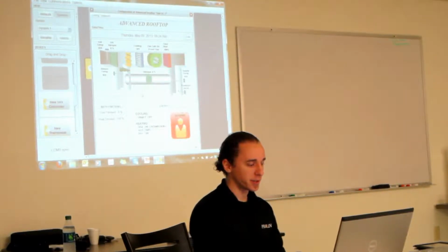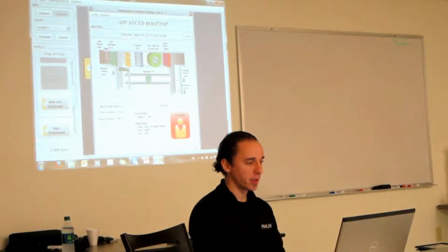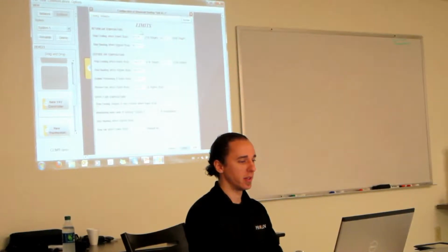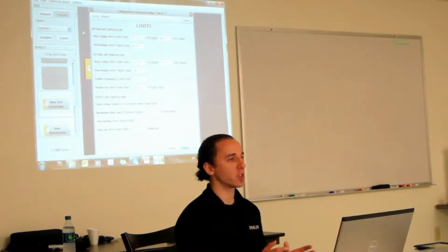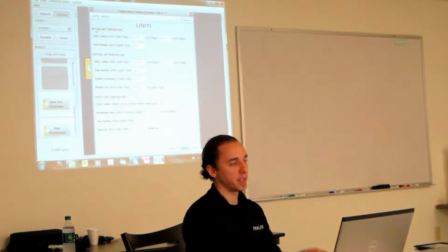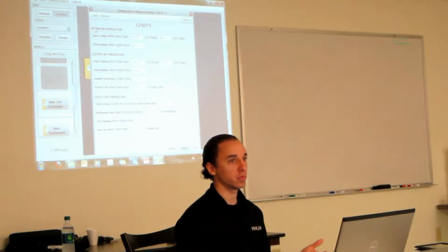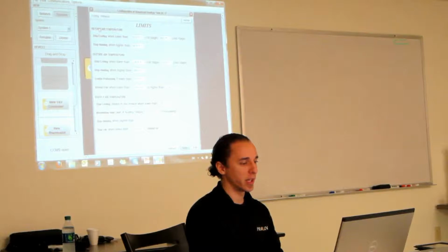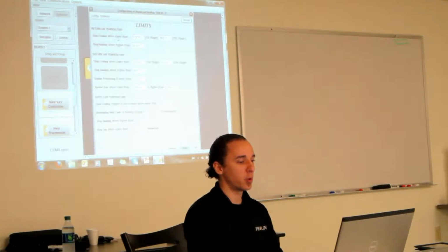Let's see what else. If I double click on any of the temperature sensors, it'll bring me to the limits page. So basically we have 3 sections to this, each section for each sensor: the return air, the supply air, and the outside air. As an example, if we're looking at the return air, we'll stop cooling the first stage when we reach this temperature in the return.